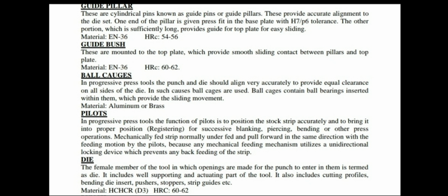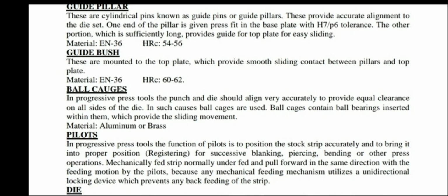Guide pillars are cylindrical pins known as guide pins or guide pillars. These provide accurate alignment to the die set. One end of the pillar is given a press fit in the base plate with H7 P6 tolerance.